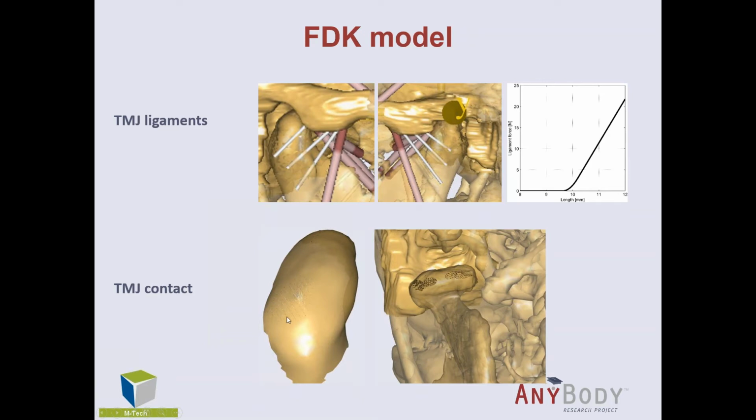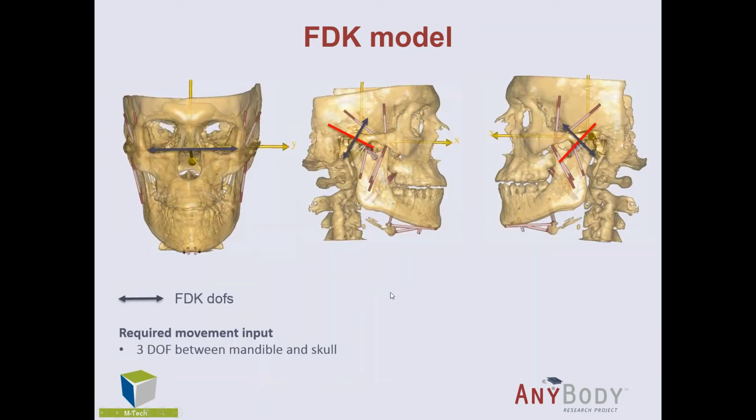So I think there should be an illustration of a series of forces down here at the top of the condyle, which is then the force in each of these nodes is proportional to the penetration depth into the other surface. So the deeper the penetration for a specific node into the other surface, the larger the force. And we assumed this to be linear elastic.